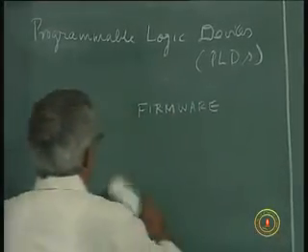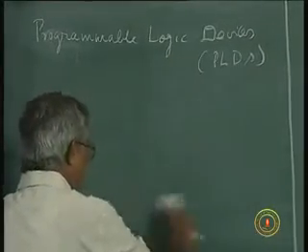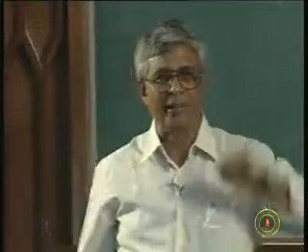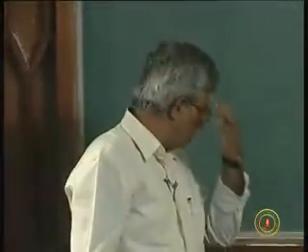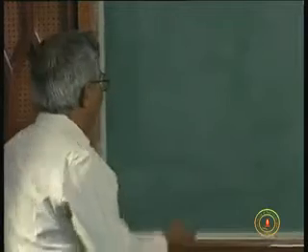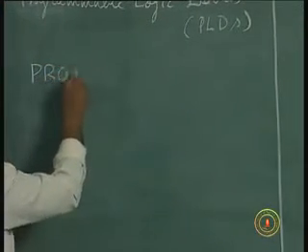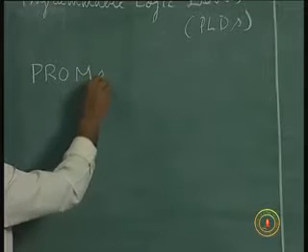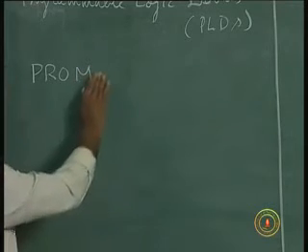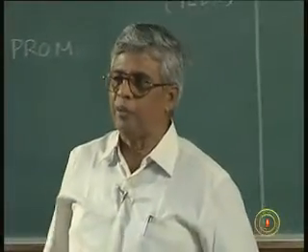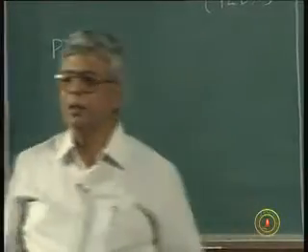Now, as I said, we already made a case for the reason for programmability, and programmability in a micro sense here, not in an application sense or a macro sense. They were originally devices known as PROMs. There are many devices which are programmable logic devices. The first one is a PROM. PROM stands for programmable read-only memory. ROM stands for read-only memory. Programmable read-only memory is a PROM.